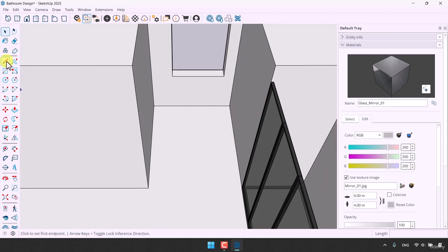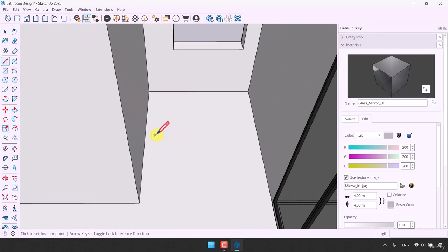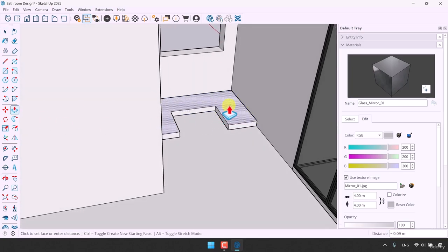So I'm going to click on the align option. I want to make some maybe continuous chairs beside this place. And how can we do this work? Very simple. You can select this edge in here, draw your line like that. Click on this line, click on the offset and take an offset of about 44 centimeters. Click on the align, close it like that, very simple and easy. And now you can click on the extrude tool and extrude it like that, about maybe 42 centimeters.